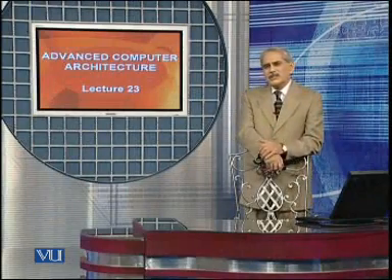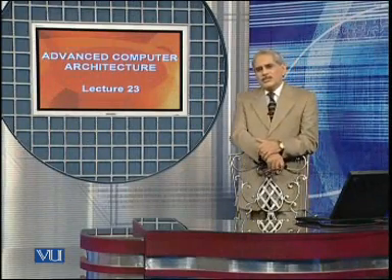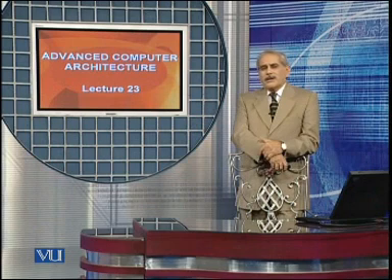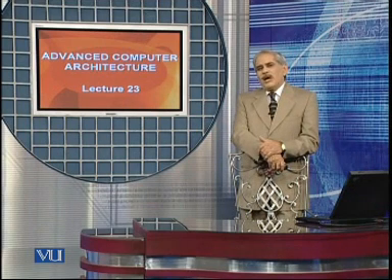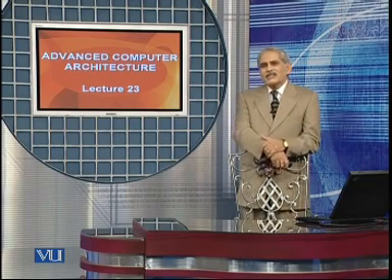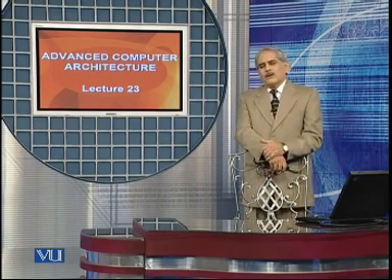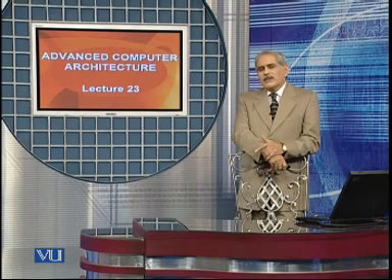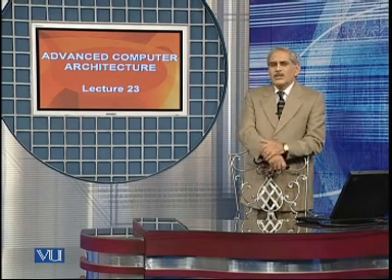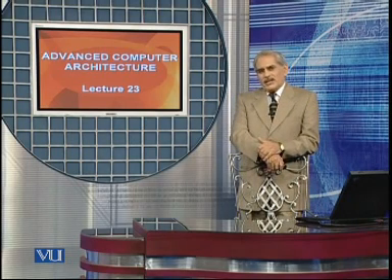If the branch is not taken, then definitely there has to be a stall before executing the second load instruction, because it depends upon the contents of R8, which are not yet available. Therefore, a stall is necessary at this place.